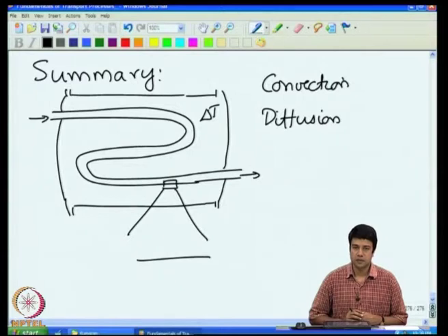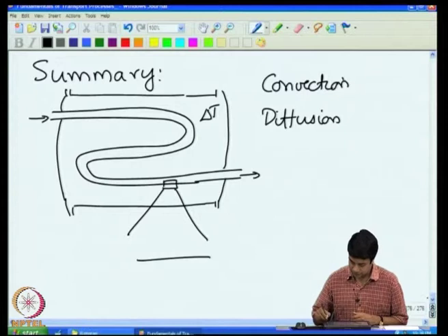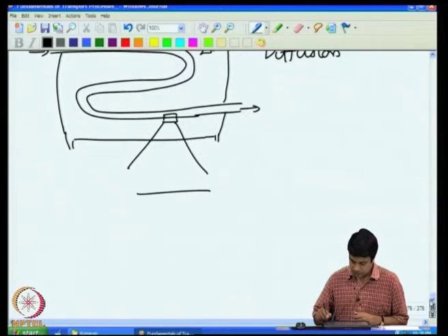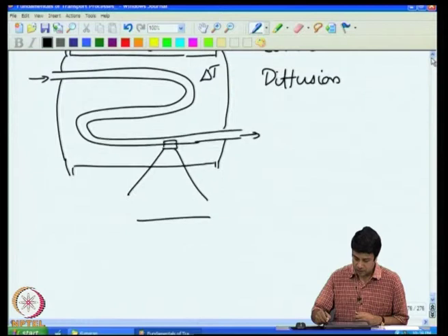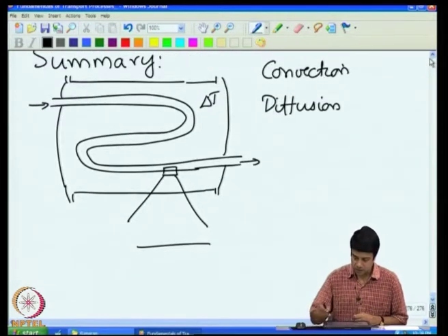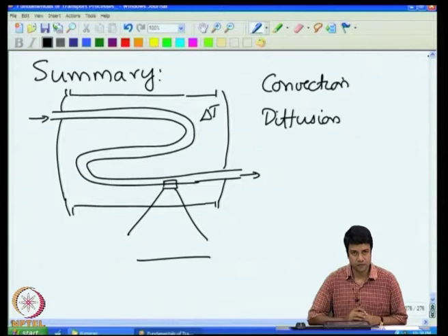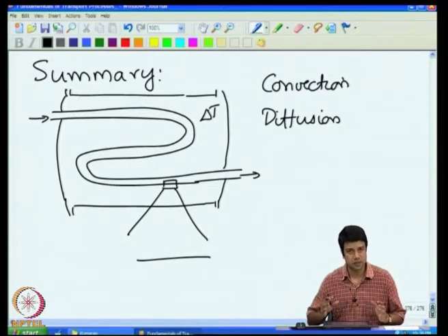Diffusion is transport which takes place due to the fluctuating motion of the molecules. Whenever you have a non-zero temperature, there is always thermal energy in the molecules. So, these molecules are in a state of rapid thermal fluctuations, and these fluctuations can also transport mass, heat and momentum. So, our idea was to actually find out the competition between convection and diffusion locally at every point within the flow, and from that to determine the performance of the entire system as a whole.